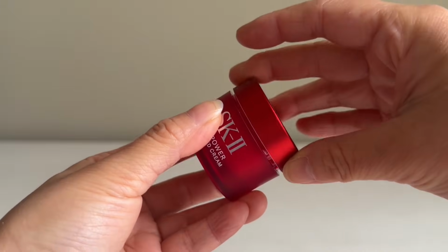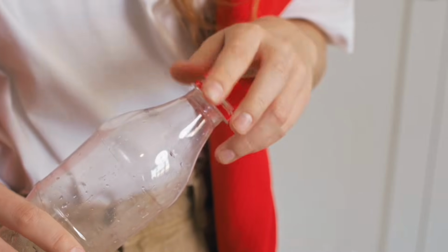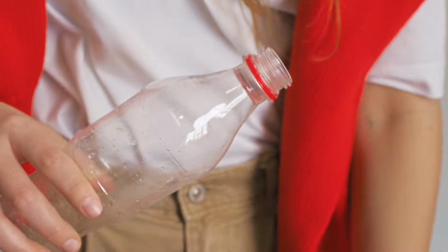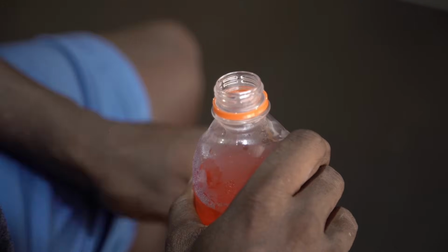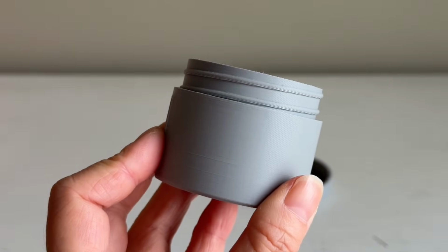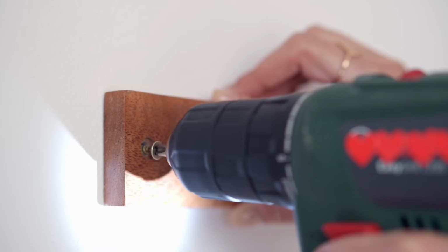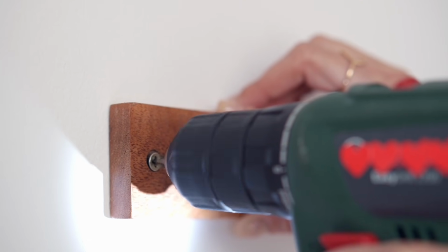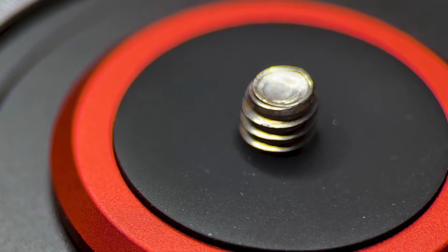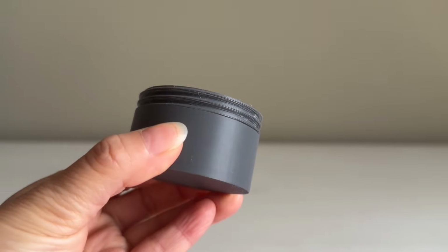Here's why. Plastic bottles are designed for manual twisting, usually opening in just a turn or two. We want some tactile feedback without the parts seizing up, and they need to account for plastic deformation and wear. That's why these threads share a few key features: a large pitch and a low thread count. Screws, on the other hand, serve a different purpose. They're for locking and resisting loosening. They have a tight pitch and many turns to maximize the friction surface, which is exactly what the thread command we used before is designed for.